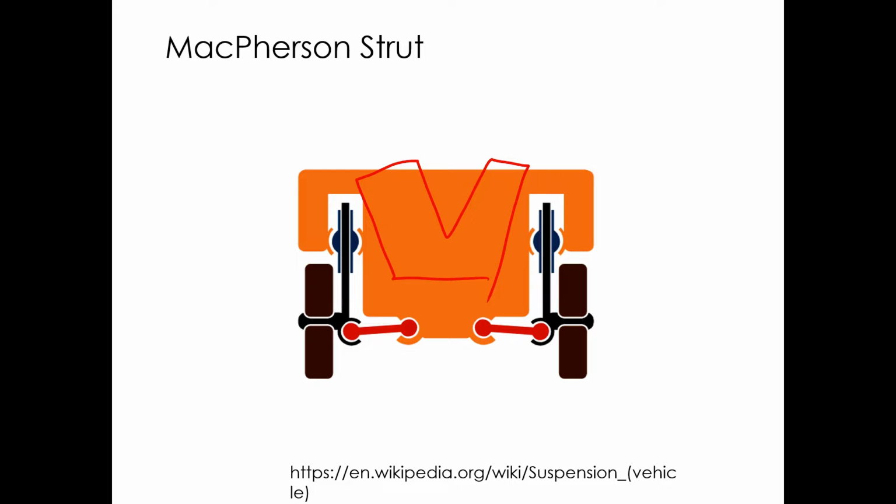You've got room. So you can also tune where the instant center is on this. You extend the lower control arm and then run a perpendicular from this prismatic joint, and extend that out and then run a perpendicular out from that, and that's going to be where the instant center is going to be. So you can tune that by where your lower control arm's at.